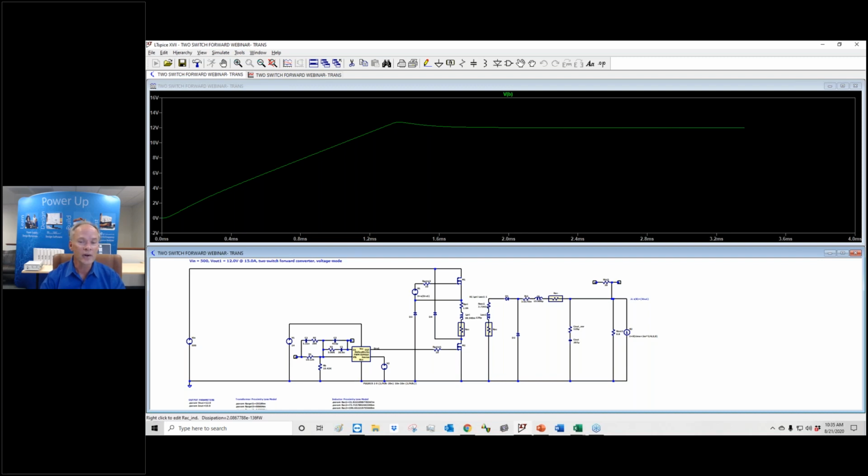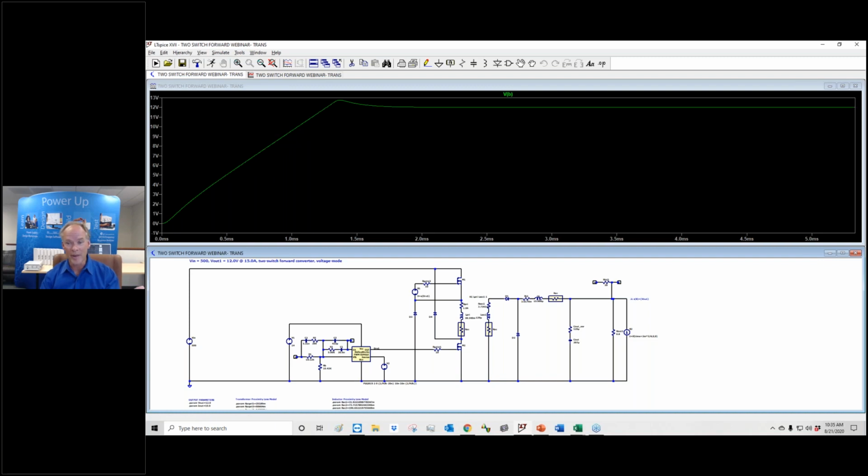And this is a very high order circuit. We've got 5 L's in the RAC in the primary, 5 in the secondary, 5 for the inductor. So there's 15 L's in the circuit. A couple more from the power stage and some C's. So this is almost a 20th order network that's being solved here. And you see it doesn't take that long.